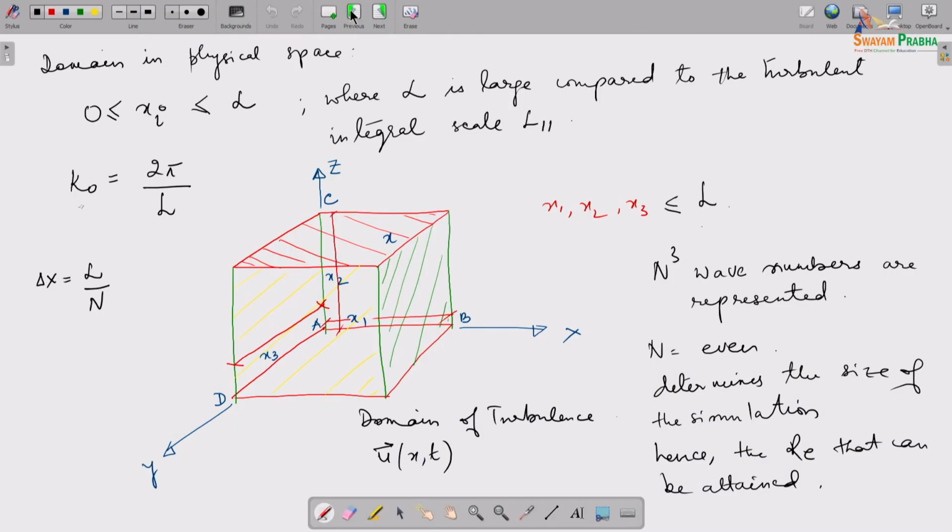Now that wave represents my velocity at this location, and this location you could think of is essentially in a physical space. It looks something like a nice little cube here, because we understand this space. Please try to understand that when I solve for those waves, this is not where I'm solving it. I'm solving that in that spectral space where I have just the waves. But when I put them together, I represent that velocity at a location which you could place in a physical cube like this one.